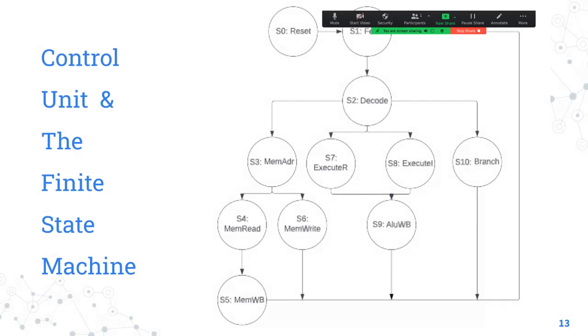Simultaneously in each fetch state, you would be setting a few control flags and then transitioning to the next state, decode. In the next cycle, you would be in decode stage, at which point you'd be setting those control flags such that the instruction gets decoded, and then you'd be transitioning to the next state depending on what you decoded. To do all this, you require one clock cycle, one time period. Based on the complexity of the task, you'd be adjusting the time period required to complete that stage before the next clock edge.